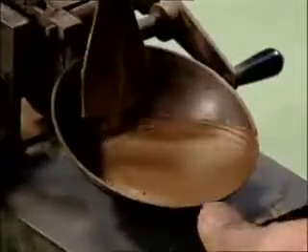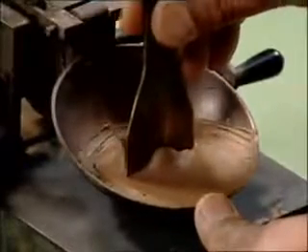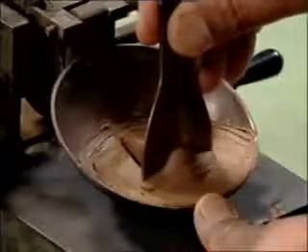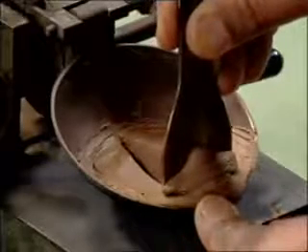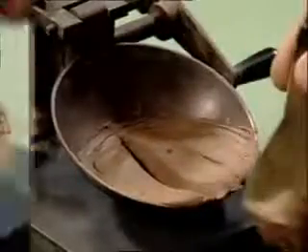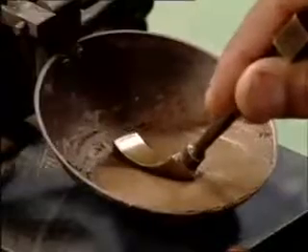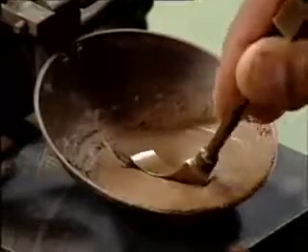As the soil is clayey, use Casagrande's grooving tool to divide the soil paste in the cup into two halves in a direction perpendicular to the axis of rotation of handle. If the soil is sandy, use ASTM type grooving tool.